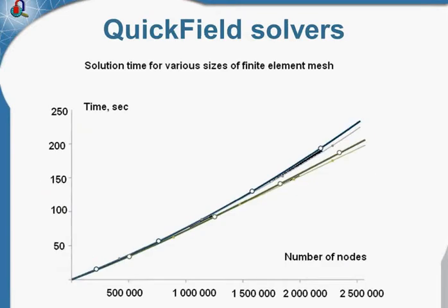Capacitor's design is often based on many thin layers of dielectric electrode composition. This may lead to large meshes of finite elements. Large meshes make the computational task very intense, and fast and efficient solvers of QuickField are of huge benefit. They are based on our special DDM procedure, which is an abbreviation for domain decomposition method, and it provides extreme speeds.